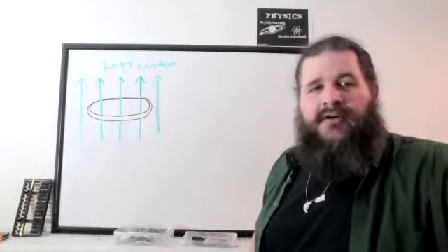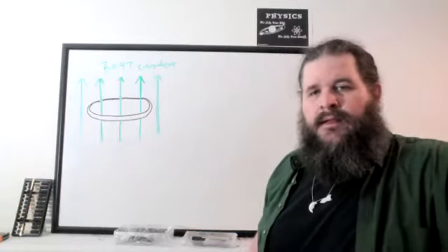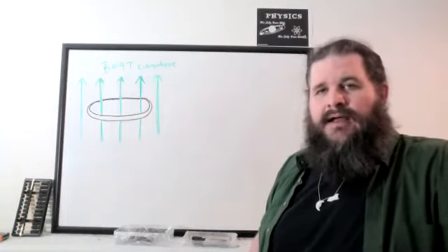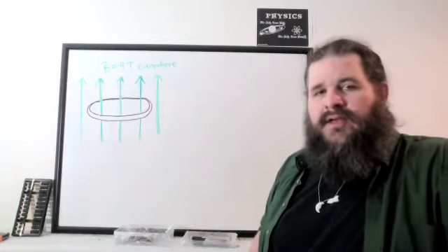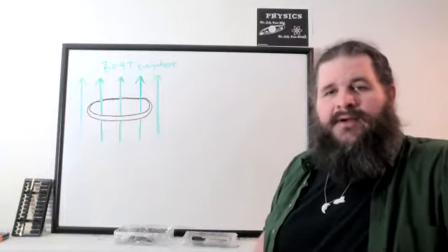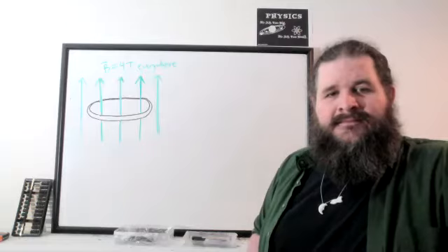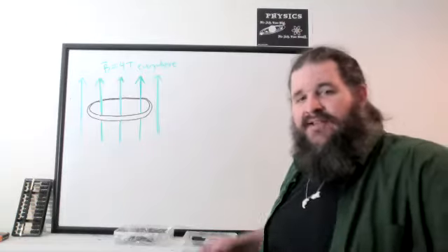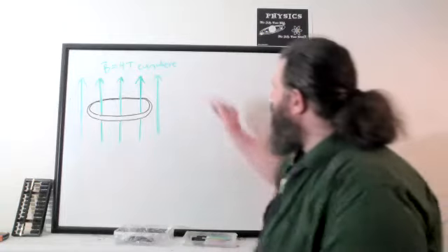So there's actually a very large amount of flux here. But if I'm just holding this still, that flux doesn't lead to any induced current, because induced voltage doesn't just require there to be flux, it requires what to be happening? Yeah, there's got to be a change in flux as time passes.